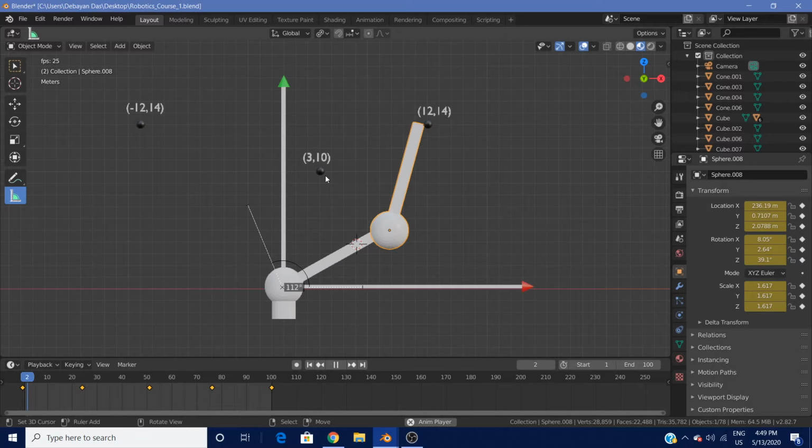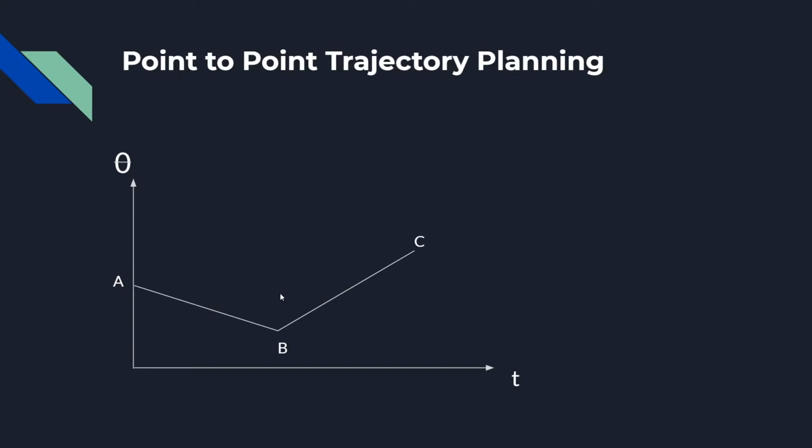So to fix that, we have different mechanisms. Those mechanisms are called the cubic spline. There are multiple. There's cubic spline, and we'll go into a few more after this. But the first one that we can talk about is called the cubic spline. And there we define theta not as a straight line. As you all know, if we were to determine theta over here, it would have been a straight line, in the form theta is equal to a0 plus a1t, right? Y is equal to mx plus c. And that is what would have been the equation for this.